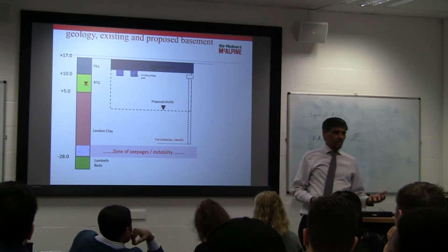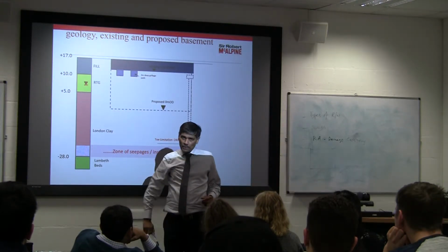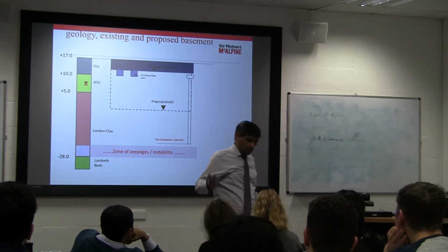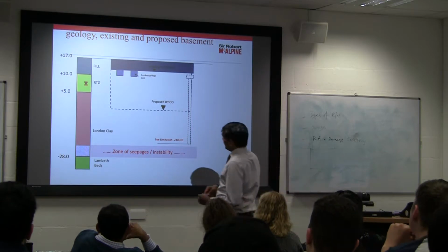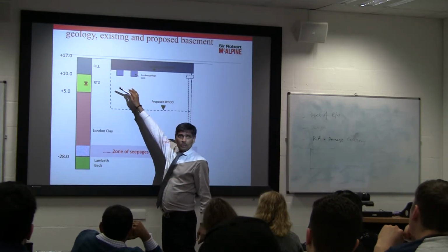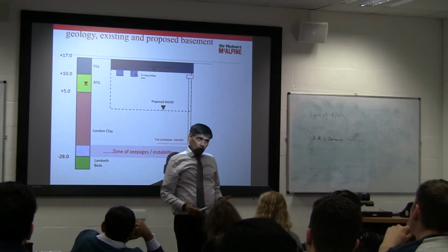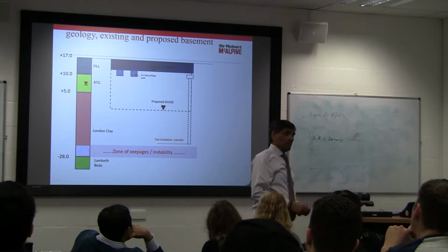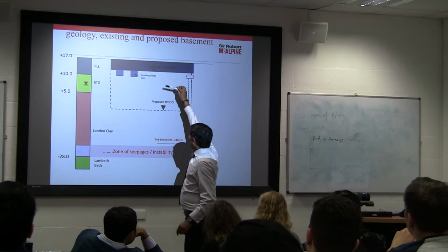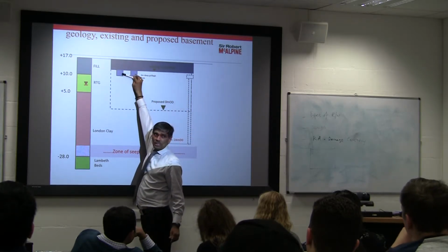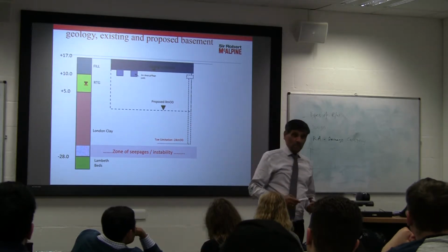So you dig them. You are working with all knowns because you are digging sequentially. You are opening up the existing foundations, because before you start, most of the time you will find existing foundations. There is no map. They can't tell you, because London has so much history of building on site again and again and again. A lot of historical stuff has happened on the site. We do not know. We find some foundations there, some foundations there. And sometimes you get good archive information, sometimes the client may not have that archive information. So another beauty of this method is as we are digging down, we are exposing these things and we are nicely dealing with them as and when we see them. So that is the beauty of it.